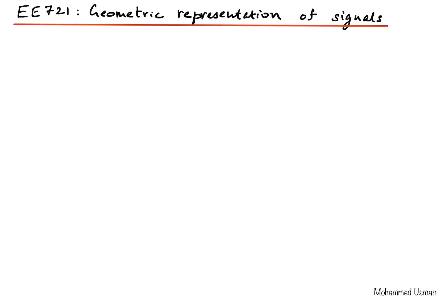In this course, we will be discussing several analytical tools and techniques that are useful in the analysis and design of communication systems. In the previous lecture, we saw one such technique of representing a bandpass signal as a low-pass signal. So we did the bandpass to low-pass transformation. The idea was that it is easier to process lower frequencies, so the bandpass signal, which is at the higher frequencies, is transformed to a low-pass signal, which has lower frequency components.